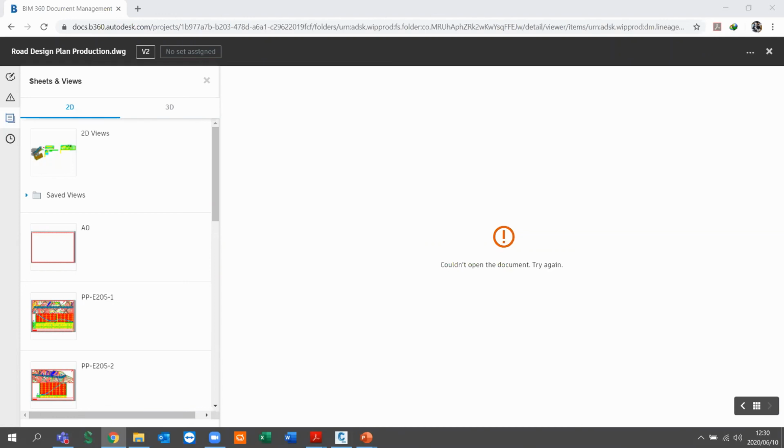Well, Michael, from what we gather up to this point, we don't have limits because Civil 3D design elements are a lot bigger than the basic Revit structures, because it has more geo-reference data, for example, CSV files and coordinates and text files. So at this point, we don't have limits in bringing in those models.